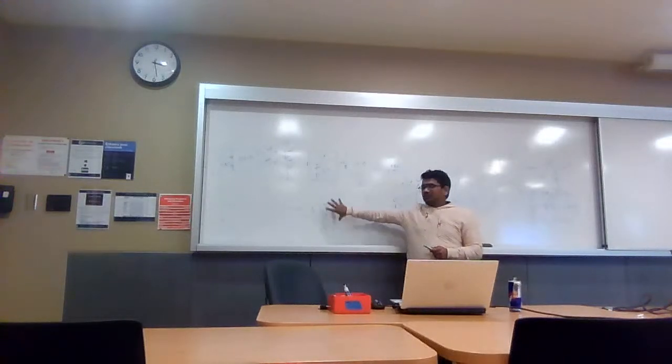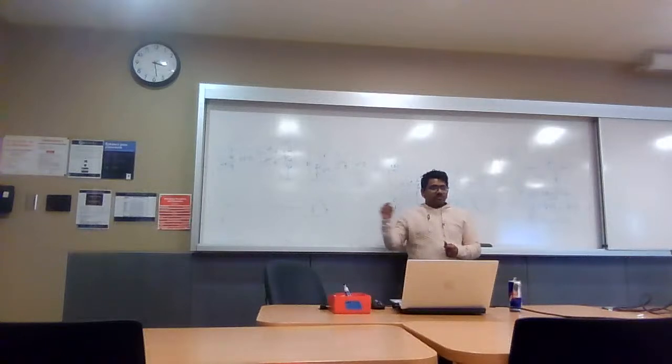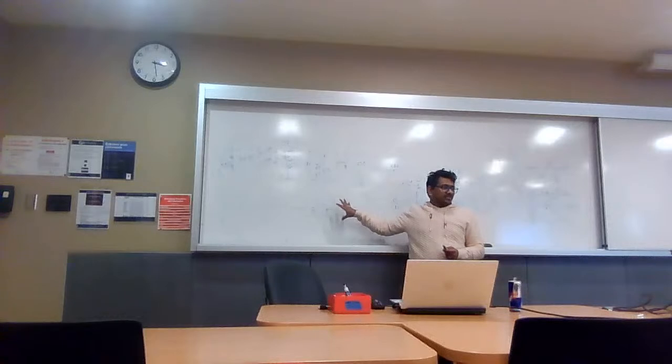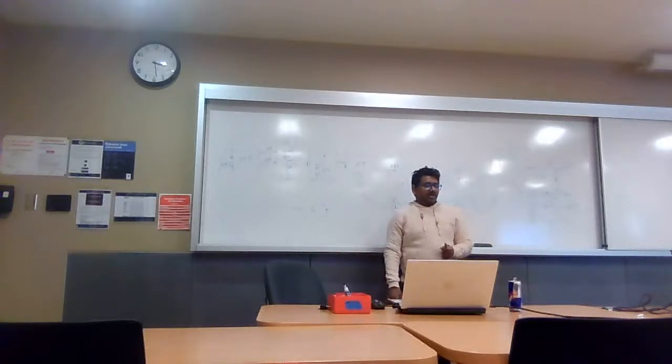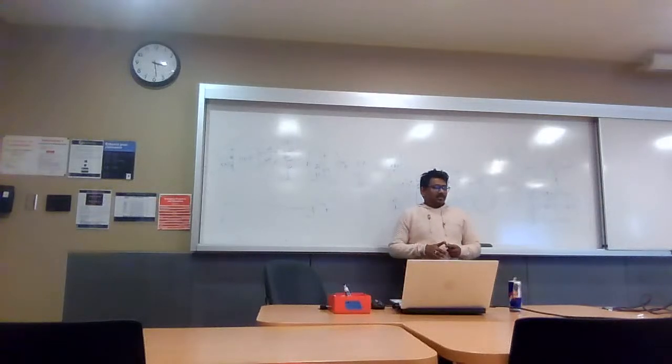The flip-flop is also an important topic. It can work like a register. I mean, it can store some value. You can also study the D flip-flop and latch. There's also an interview question: what is the difference between a D flip-flop and a latch? The basic difference is that the flip-flop works depending on the clock. If there is a clock, then this flip-flop works. On the other hand, the latch depends only on the level.